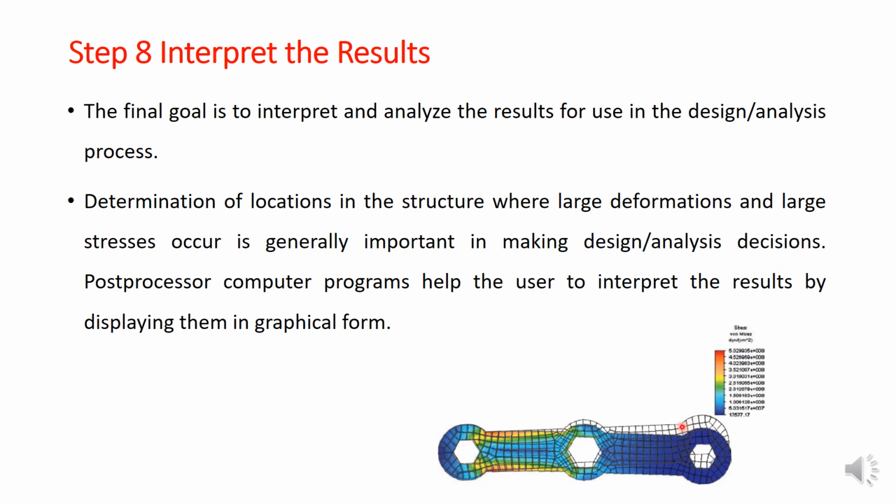You can see a number of meshes here. You understand from this figure that initially we have this wrench, and we divide it into a finite number of elements, or discretize it with suitable elements. Here we have used mostly quadrilateral elements for discretization. After this, we establish elemental stiffness matrices for each quadrilateral element. Then we combine all these elemental equations into a global equation, and we apply the boundary conditions, such as where it is fixed.